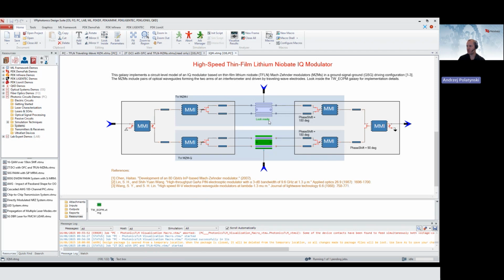So as I showed, this was just the modulator, so we need to really build the Mach-Zehnder with adding additional waveguides and MMI connections, and by cascading 2 of them, one for I and one for Q, you can see the complete design of the modulator.